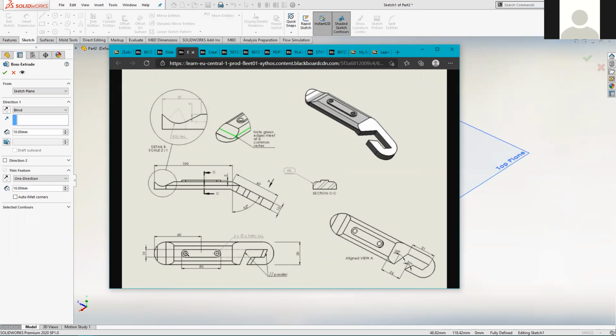So yeah, 30 mil, and I would regard it wise in this instance to put one of our base planes down the center of this part. Because whilst this part isn't 100% symmetrical about the center line, it is largely symmetrical. There's only this cut at this end that breaks the symmetry. So it would probably be useful if we ended up with one of our base planes running horizontally on this view down the center of our part.